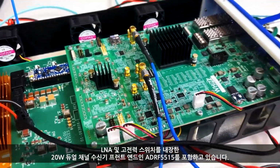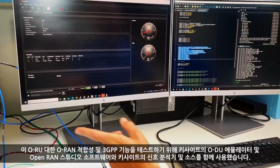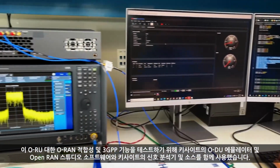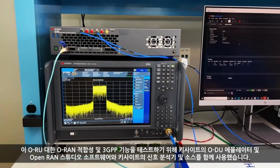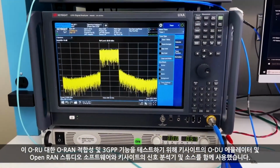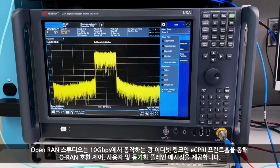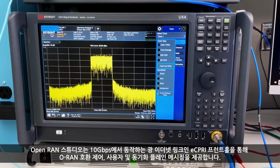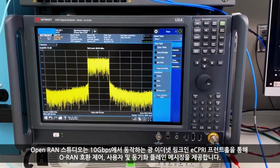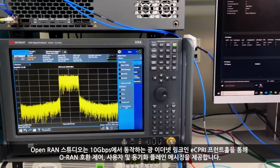To test the O-RAN compliance and 3GPP capabilities of our O-RU, the Keysight ODU emulator and Open RAN Studio software is used together with Keysight signal analyzer and sources. Open RAN Studio provides O-RAN compliant control, user, and synchronization plane messaging over the eCPRI front haul, which is a fiber optic Ethernet link operating at 10 gigabits per second.